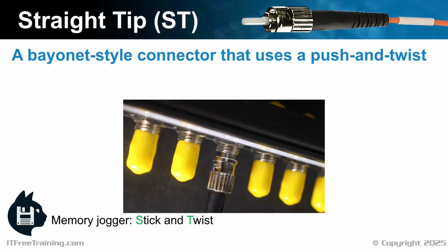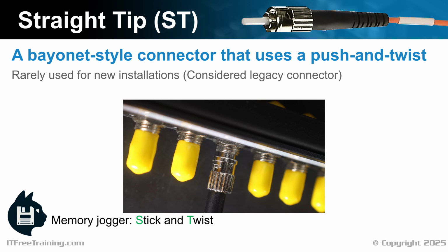The ST connector was a staple connector in early telecommunications infrastructure and is still present in older telephone networks. While historically significant, it is now largely outdated and rarely used for new installations. When used, it is generally for multi-mode networks, so you will most likely find it in older buildings and older data centers. You generally don't find it used in long-distance lines.